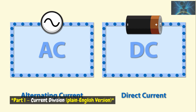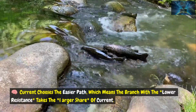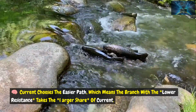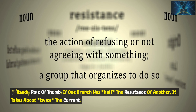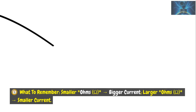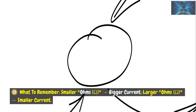Part 1. Current division. Plain English version. Current chooses the easier path, which means the branch with the lower resistance takes the larger share of current. Handy rule of thumb: if one branch has half the resistance of another, it takes about twice the current. What to remember? Smaller ohms, bigger current. Larger ohms, smaller current.